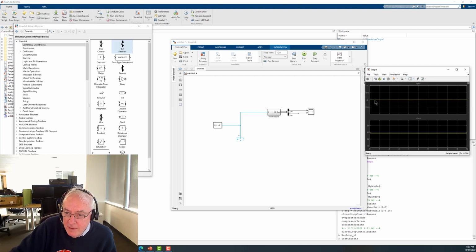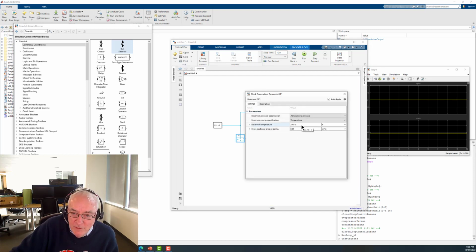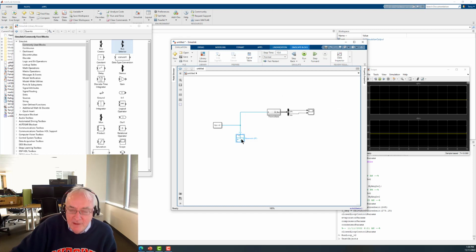And I can rescale that, and I'll see pressure at 0.1. And if you're familiar with the units of megapascals, you'll know that 0.1 is very, very close to 1 atmosphere, right? So that's our default value on it. And the enthalpy, again, for our standard temperature that we're using, 293.15, for the fluid that we're operating with, that's what your enthalpy will be. Also, again, at atmospheric pressure. All right, and so now I want to be a little bit more specific, like, where did all that come from?